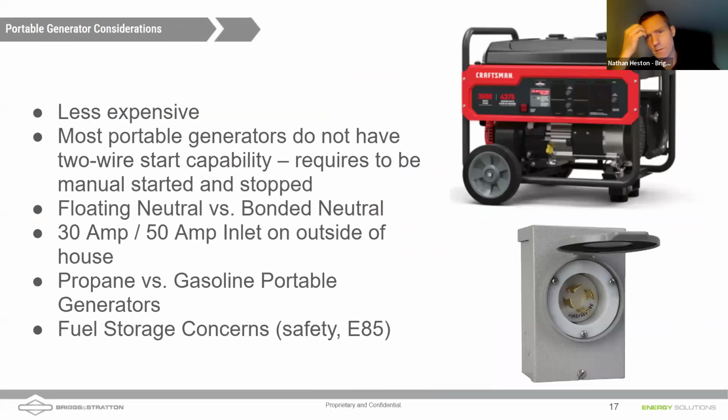What does this look like? Are we selling Craftsman generators, Daniel? What are you showing this for? That is one of our portable generators. I get this question a lot, Nathan: can I use a portable generator to feed into a Solarc? You can. It does need to be a 240 volt generator.